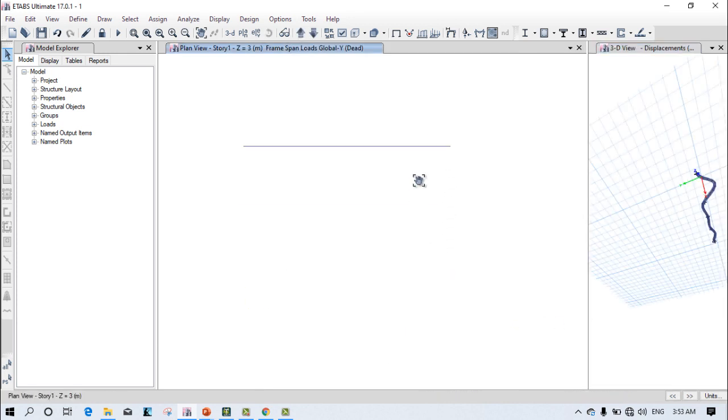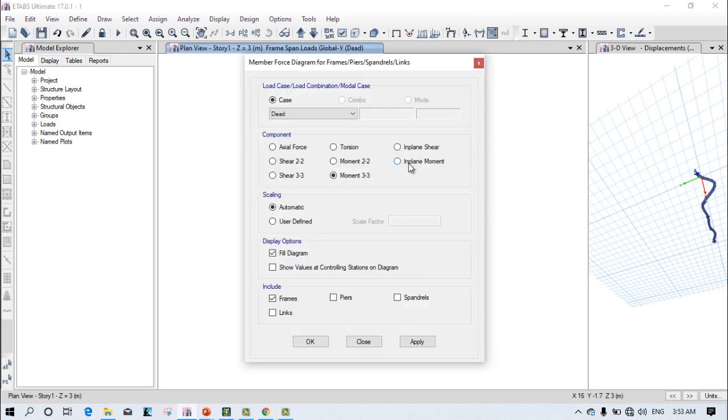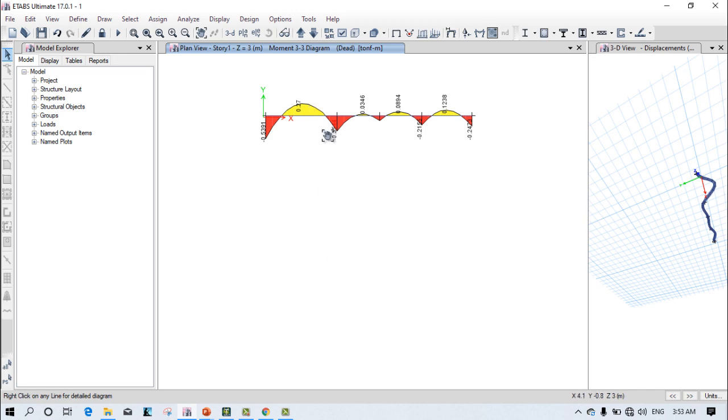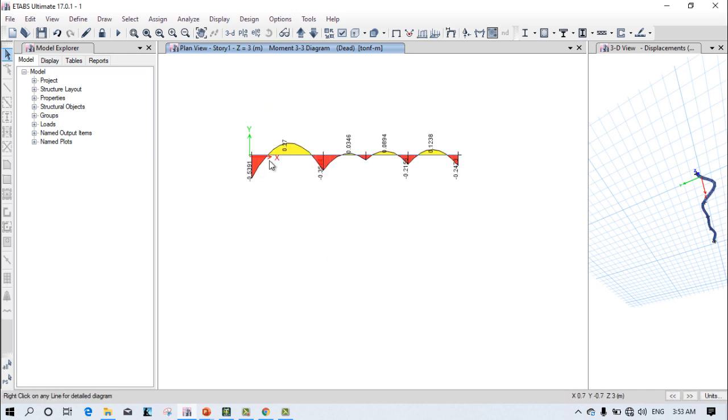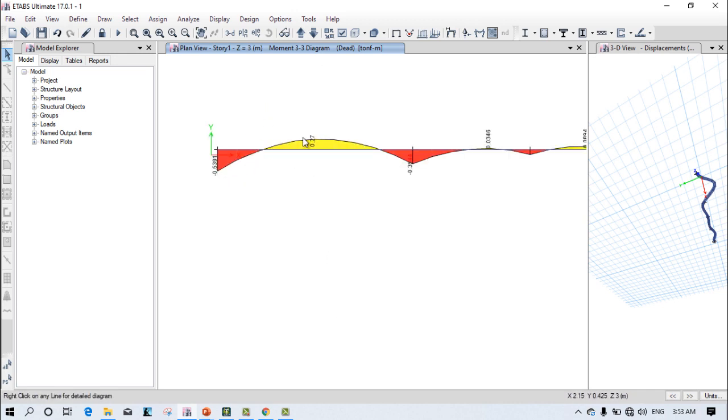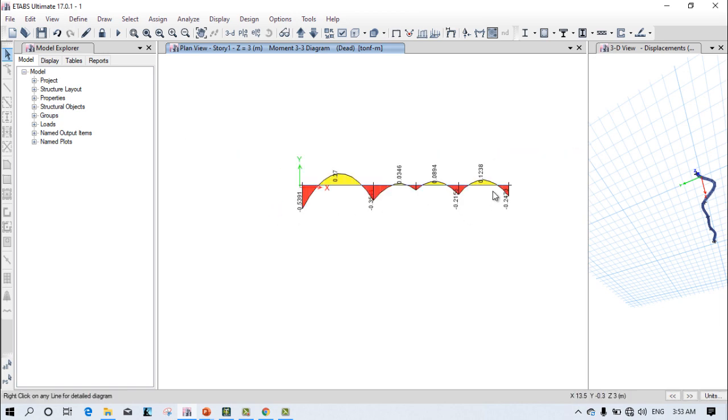Okay. So now just see the shear force and bending moment. Just select here. The moment we will check with respect to value. Apply. Okay. You can see the bending moment. The bending moments are very low, not very high, so it's okay with this. We can go with the design pattern. If it is 0 point something, it means it's okay for us, but if it's 20, 40, 80 like this, it makes a few impacts, because 0.27 kilonewton meter is a good value.